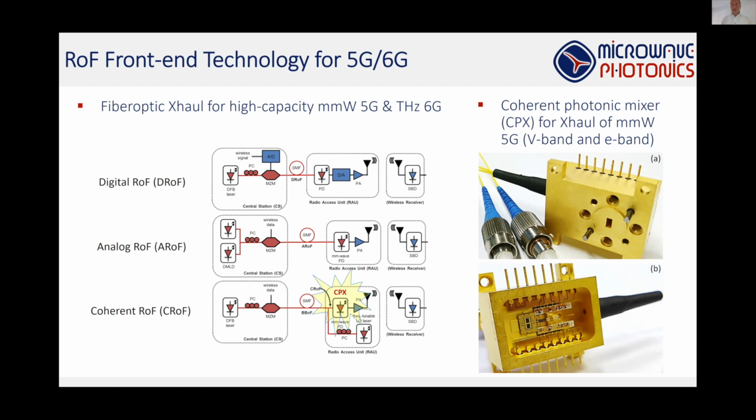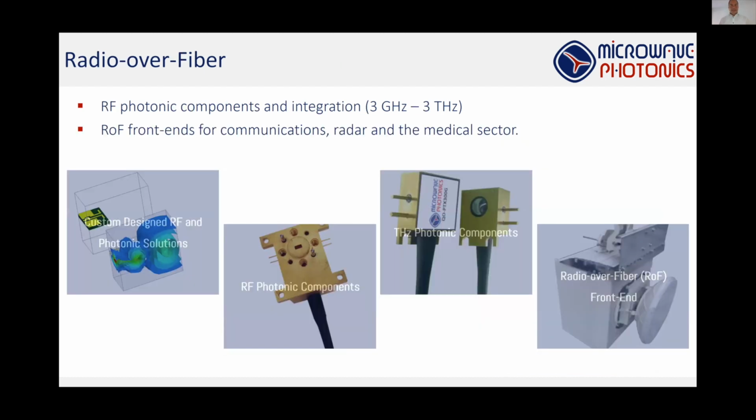What you see here especially is for E-band frequencies, the maximum output power that we can reach is 15 dBm. With that system, we can bridge several hundred meters to kilometers of air, for fixed wireless access applications, as I will show you in a second. Other components that we are addressing even go up to the terahertz frequency range. In that case, we have an integration technology that allows us to integrate our chips with antennas and also with lenses in order to achieve terahertz radiation.